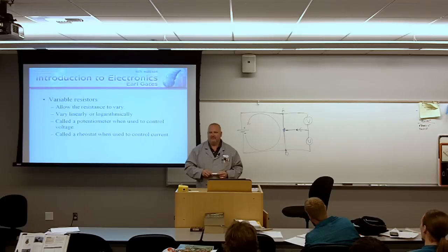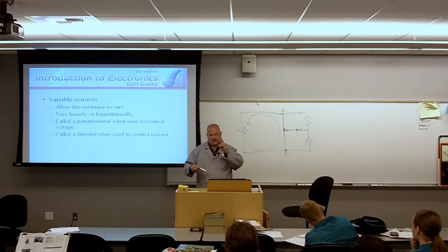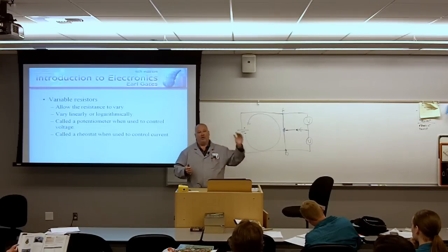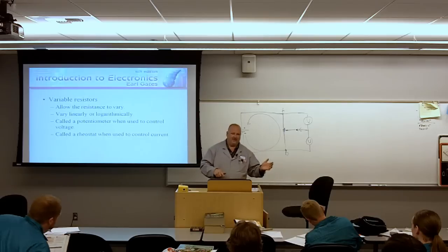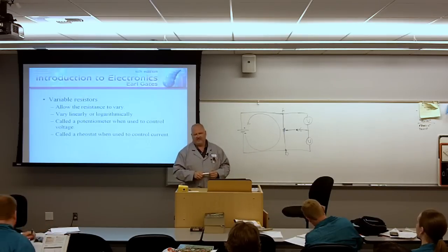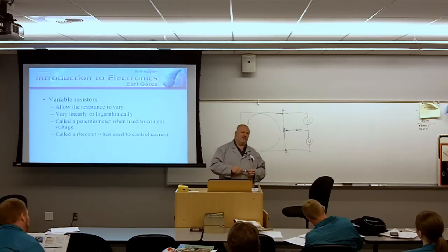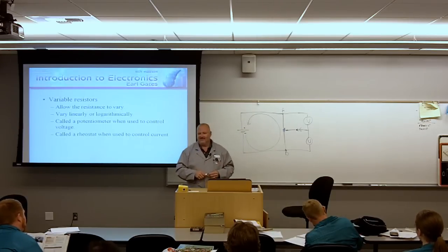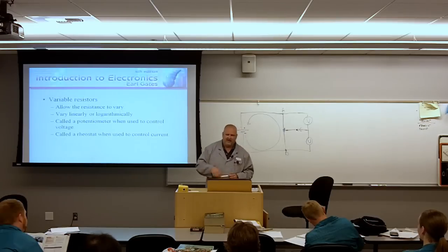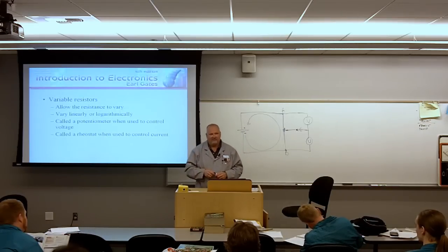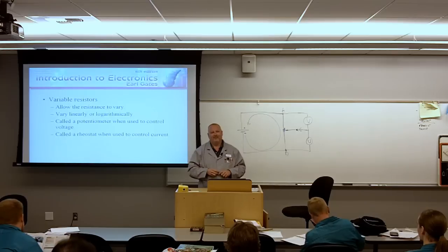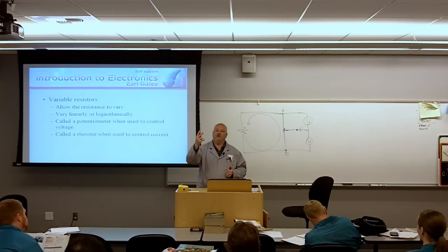How would I do that? Only connect 2 of the terminals. So if you go to Radio Shack and say, do you have any rheostats here? That would be a fun question. I should give you that as an out-of-class assignment. Everybody go to Radio Shack and ask if you got any rheostats. And they'd probably scratch their head and say, oh, but we have some potentiometers. You could use a potentiometer as a rheostat. You only need to connect 2 of the terminals.